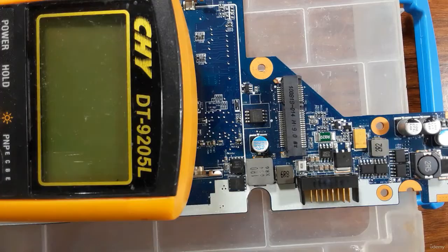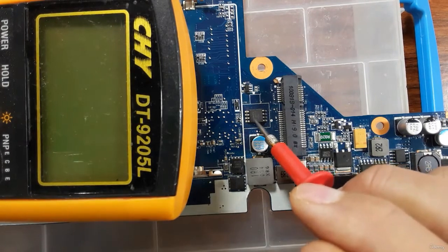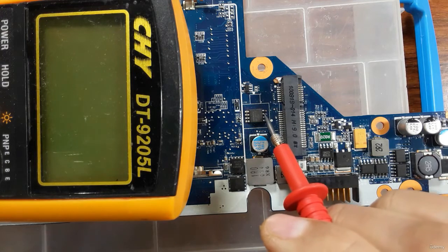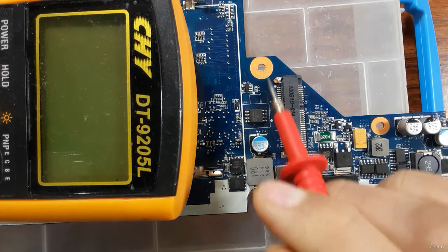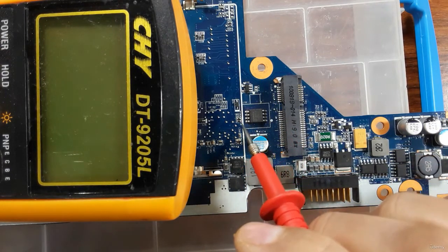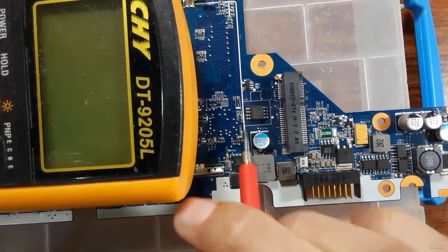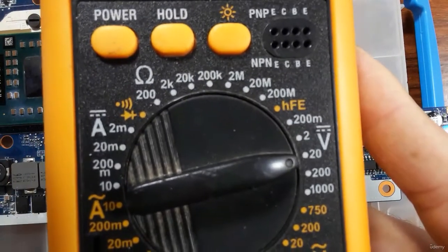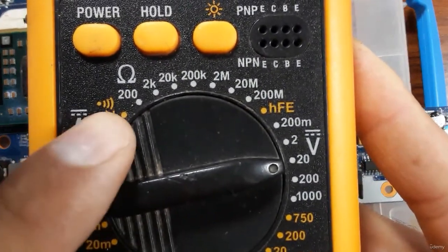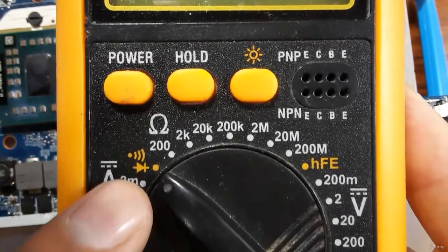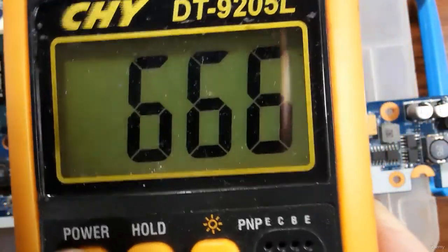Okay, so as you can see in this laptop motherboard, this is the BIOS. This dot means this is pin number 1. Then pin number 2, 3, pin number 4. Pin number 4 is always connected to the ground. We will check it. Then pin number 5, 6, 7, and 8. Pin 8 is always connected to the VCC. So to check the BIOS, let's use the multimeter. Let's first put the multimeter selector to the buzzer option, or the continuity option, and then press the power button.